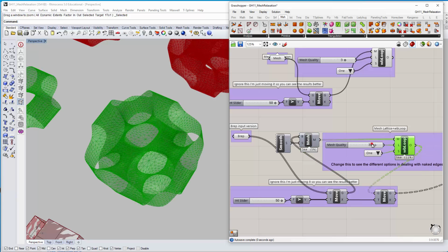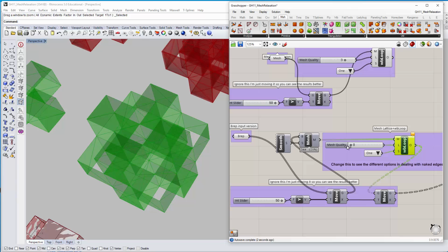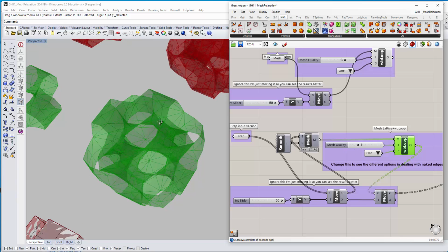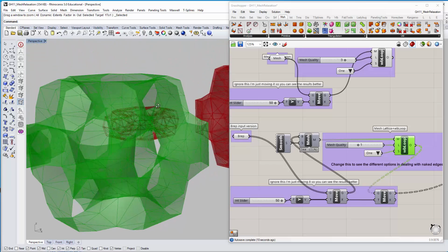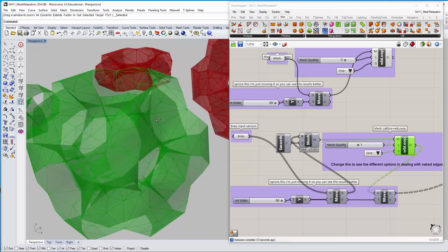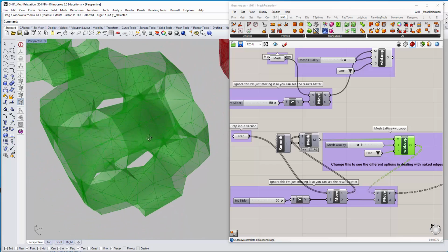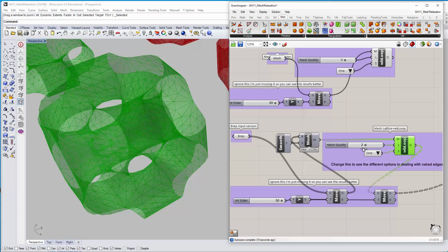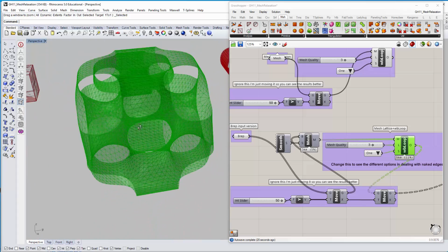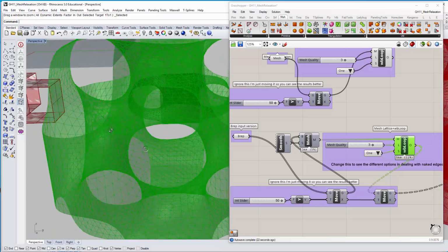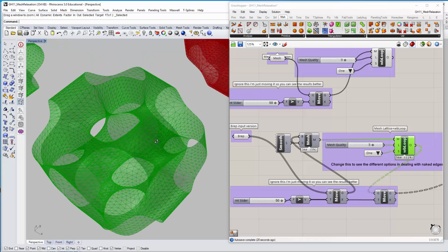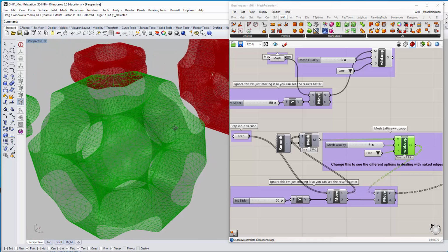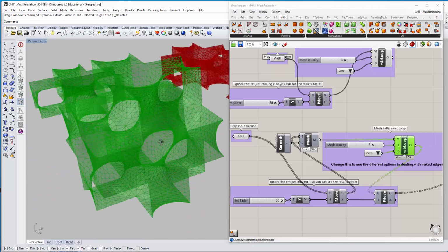Pushing it through the Weaverbird loop, same thing, look at this. So it goes from the original one iteration of subdivisions, and this is the loop, so it's making triangles out of those flat faces while keeping all the faces interconnected. Second iteration, third iteration, and now you're getting something that's really interesting as a sort of continuous looping in and out surface. Sort of like a Mobius strip, except in 3D as a 3D sort of cellular geometry. You can play around with these, but you would get slightly different results.